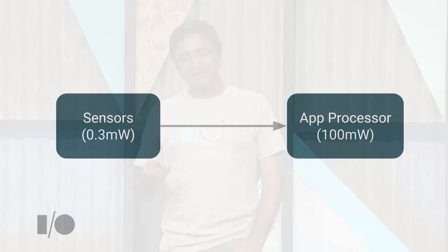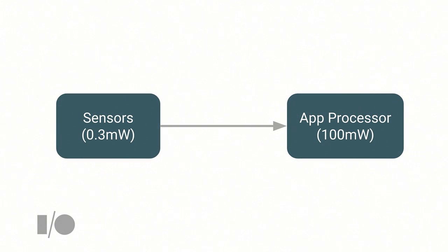On many devices, there's a multi-layer approach to processing, at least as far as sensors are concerned. At the very source, there are sensors like the accelerometers and the gyroscopes. Sensors today have come a long way from years ago and themselves consume very little power. They're really power efficient. Accelerometers and gyros today take less than a milliwatt to sample data. They embed smart algorithms like gestures and motion detection. Some even have rudimentary programming frameworks for customization.